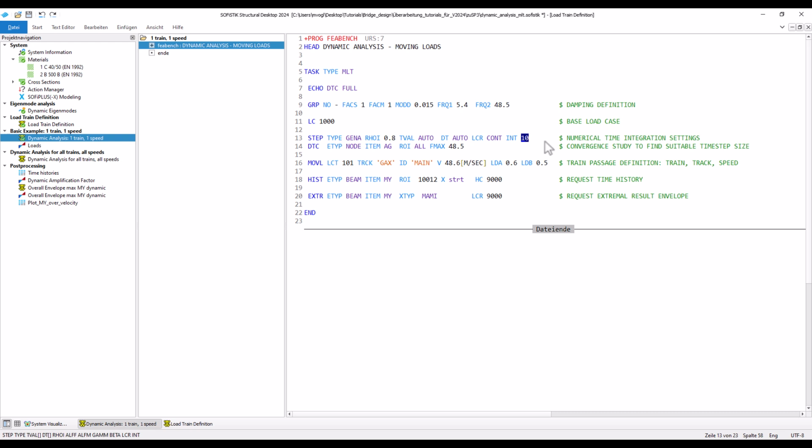If you have a small time step for accuracy reasons of the numerical time stepping, we nevertheless might not need the results at every step and could select a coarser storage interval with this setting. As the storing of the results takes some time, this is a reasonable way to speed up the analysis. We will also come back to this point in the next section.